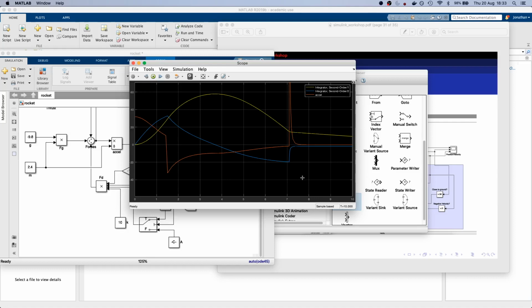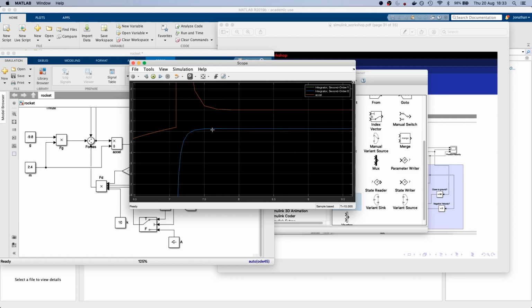You know, your parachute deploys, you jolt, and that's that jump in acceleration. And quickly, that drag force is slowing that rocket down. Look what happens to the velocity. It goes from a high negative value to a lower negative value, and now it's taking so much longer to get down to the ground. Here's our position, falling very slowly. Instead of its terminal velocity before, its terminal velocity is about minus 1.8 meters per second with that big parachute deployed.